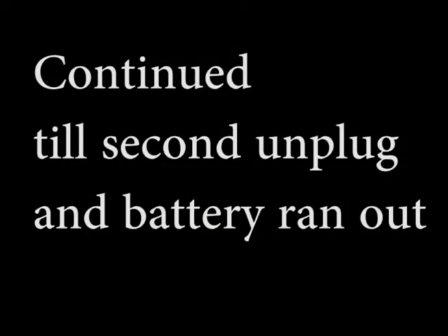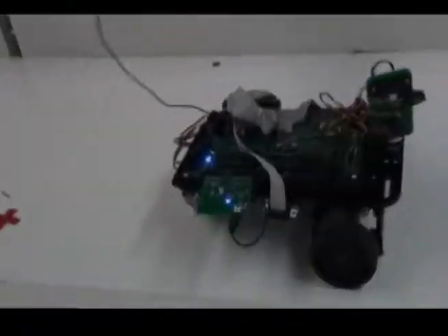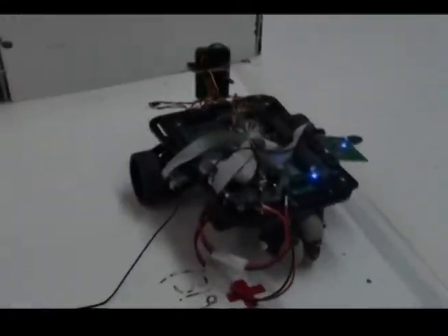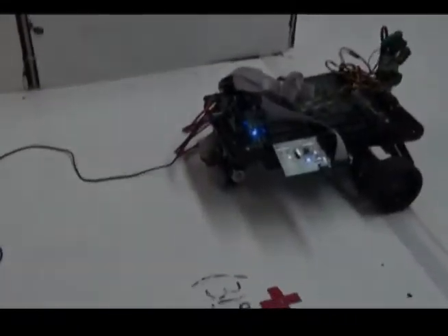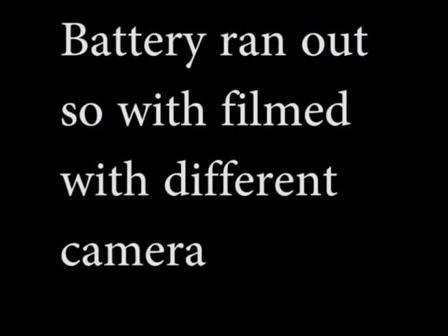Next, we're going to talk about the trajectory, which is the wavefront function. We implemented the wavefront algorithm to be able to navigate to the designated location we wanted. The task required us to move to the final goal using 5 waypoints. We update the wavefront every time we scan and sweep, and the wavefront goes from the starting location to the waypoint. Every time it updates, the current location becomes the starting location, and it uses the current location to navigate to the goal location.